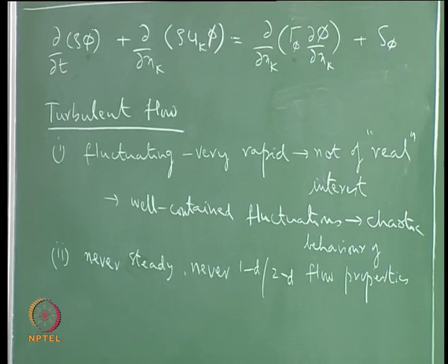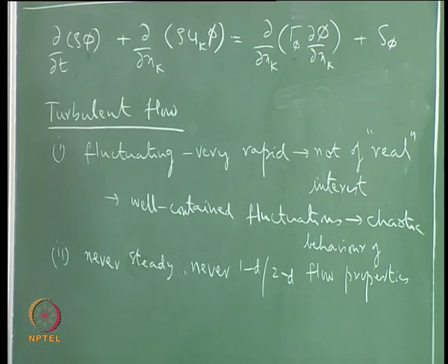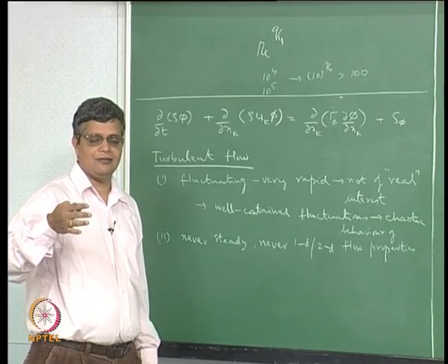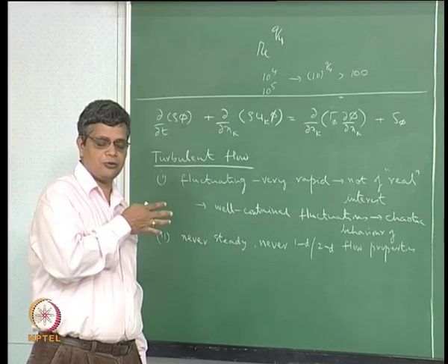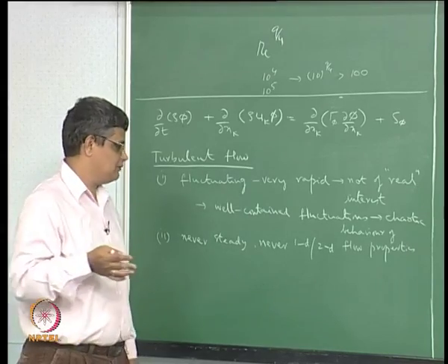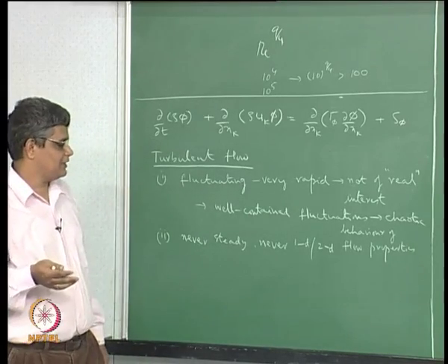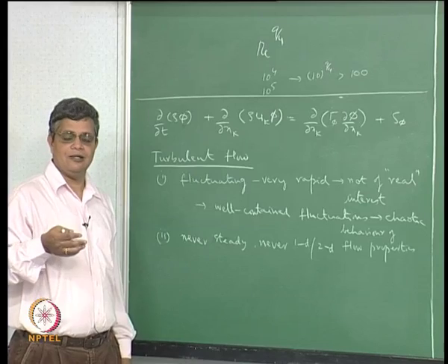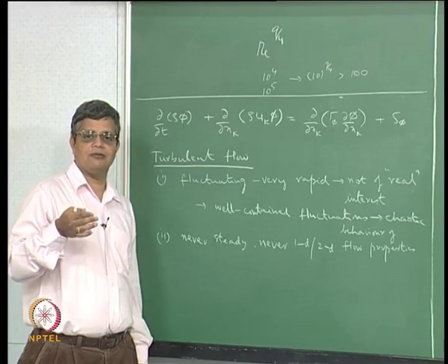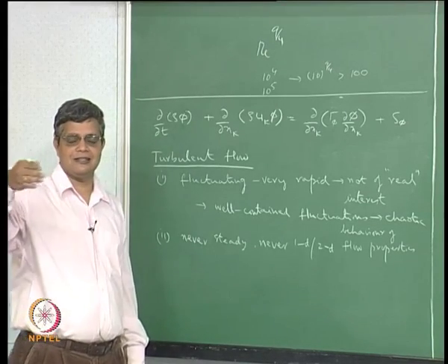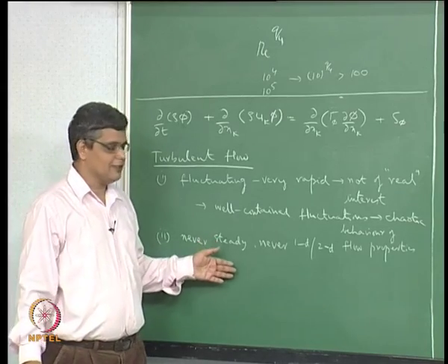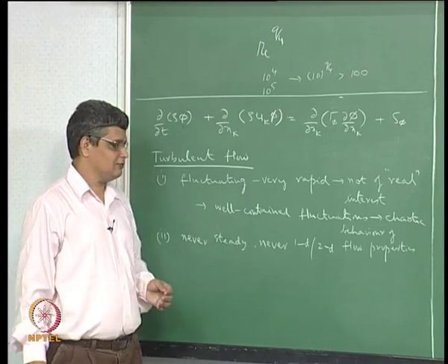Even when you have the typical assumption of fully developed one dimensional flow, fully developed flow through a very long pipe with constant properties and constant pressure gradient and so on, even then, in the normal case when we do not expect any variation in the flow direction, in a turbulent flow there will be variation in the flow direction.